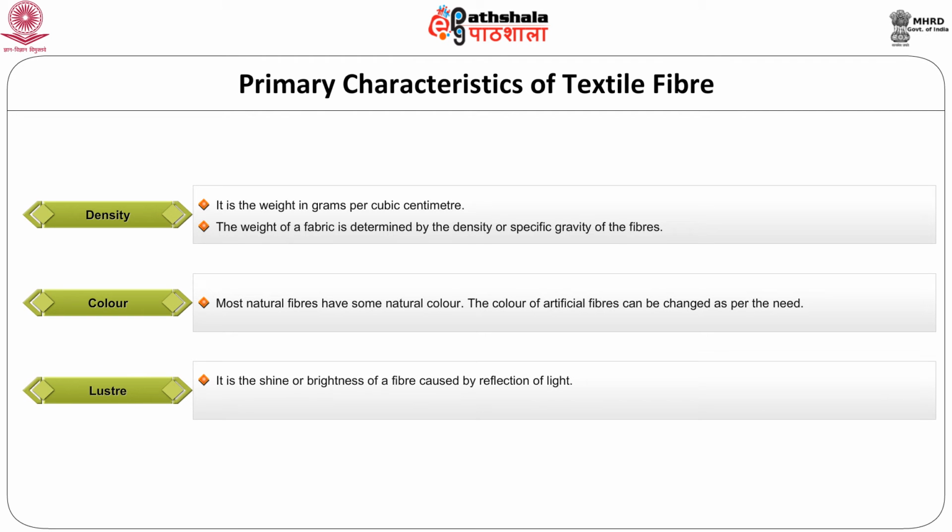Luster. Luster is the shine or brightness of a fiber caused by reflection of light. The physical structure and shape of the fiber influences the luster. Smooth fibers reflect more light than rough or serrated fibers. Round fibers reflect more light than flat fibers.